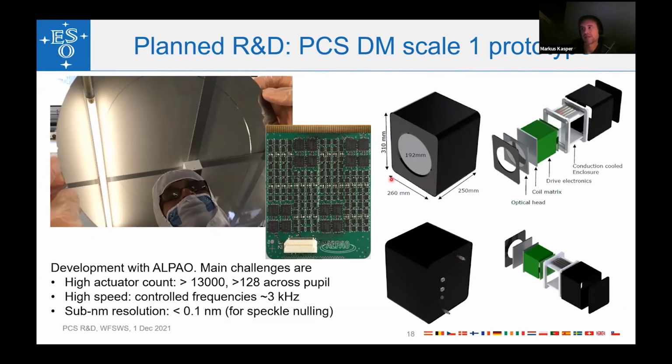So these things exist. Alpao has already worked on integrating their control electronics into the mirror housing. That's a very nice feature for this deformable mirror of about 20 centimeters diameter. All the electronics could be in the housing, so you only need an optical signal connecting directly to the DM case, without all the high voltage cables and channels going to the DM.